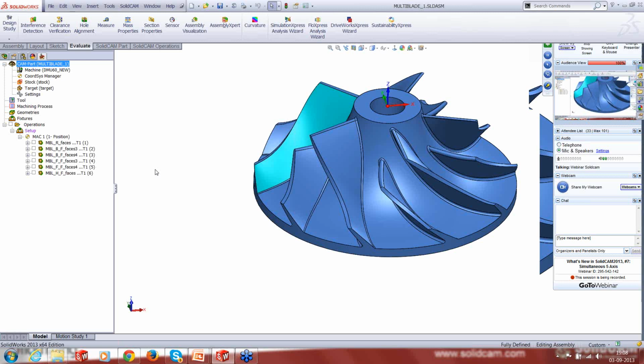They continue this question because we have the incline line option inside Swarf and Contour 5-axis. So for trimming, both options look good. When you're trimming a part, you use the tip of the cutter. But when you're doing the swarfing, you use the side of the cutter. So inherently, both technologies are different.